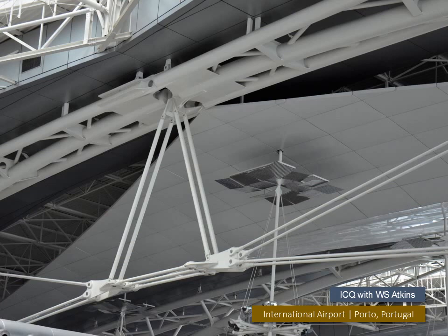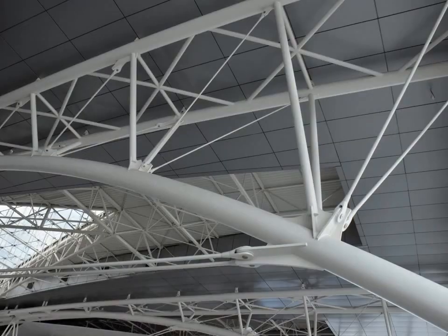The design for Porto International Airport continues in this established tradition of force differentiation to create a highly energetic arch system that spans across the departure hall. So in the instance of the design for the Porto Airport, this has allowed for the use of much thinner rods to stabilize the structure. It is pretty clear here that the curved bottom chord of the truss is a compressive member by its size, and that the horizontal ties are in tension. The tubular web members of the truss are acting in compression, but can be smaller due to the decreased compressive loading.